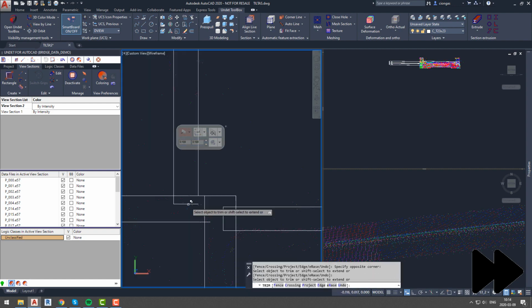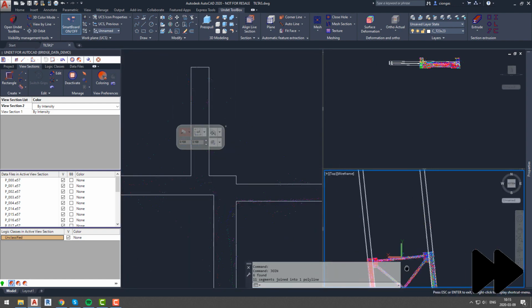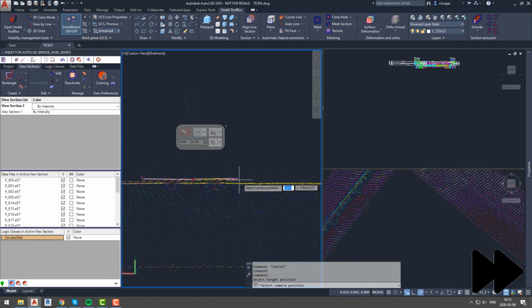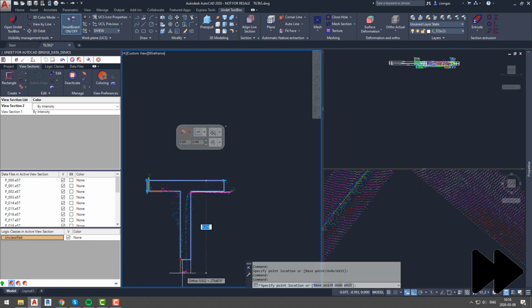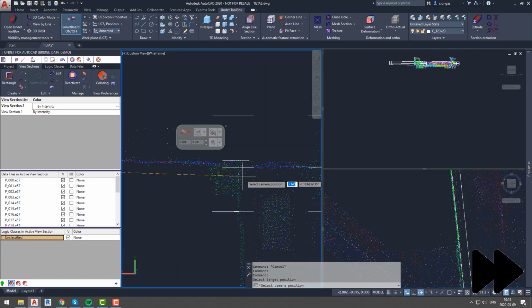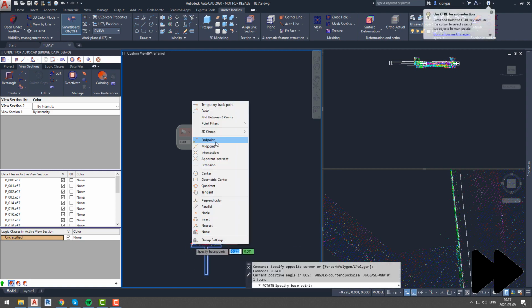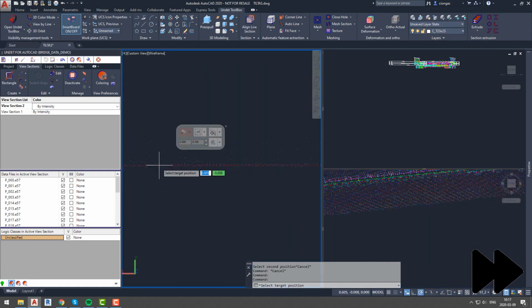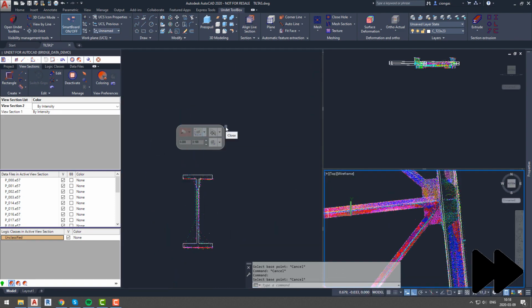Since these beams are mostly irregular shapes, we will model them using rectangles and poly lines instead of dynamic blocks. It is all up to you, if you want to draw element profile and extrude it to correct position straight away, or if you want to draw all profiles at once, and then extrude all of them at the same time as well.